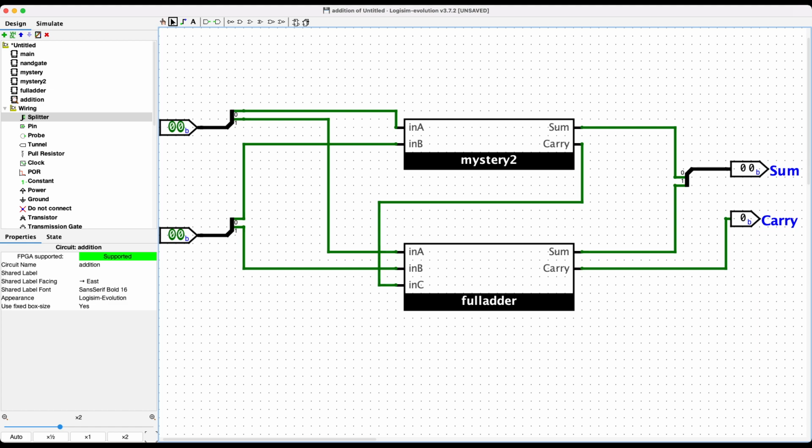Now the other thing that we have to talk about is, let's say that I took 64 of these full adders, put them in a chain, and wired them all up. And I take 2 64-bit numbers and put them into my 2 inputs. Am I going to get a 64-bit output and a possible carry bit? Sure.